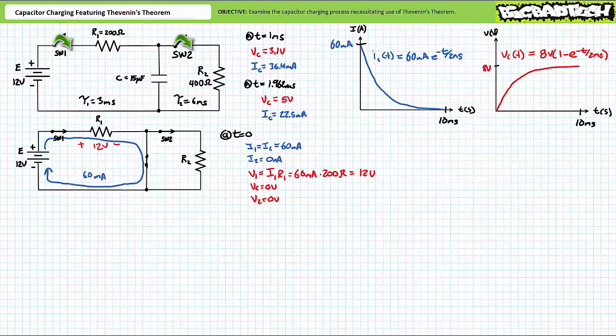This model can be used to determine the electrical properties of the remaining elements in the original series parallel circuit at t equals 0. A Kirchhoff's current law analysis of the series circuit at t equals 0 demonstrates that R1 will experience the same current as the capacitor, as no current will travel through R2, because any current bound for R2 is instead diverted through the short. No current travels through R2, and there will be no voltage across it.